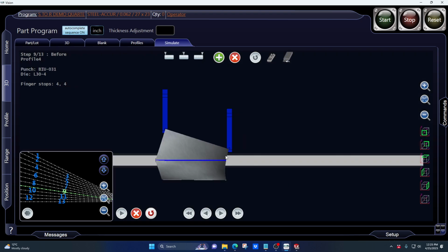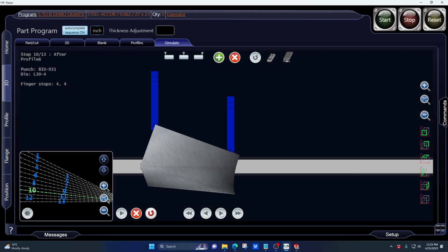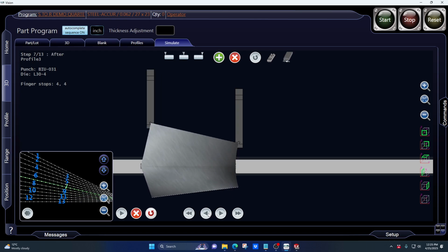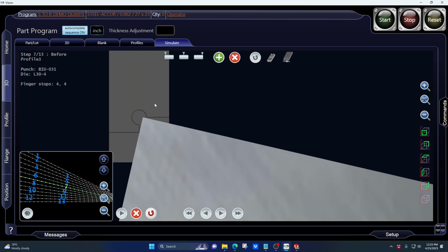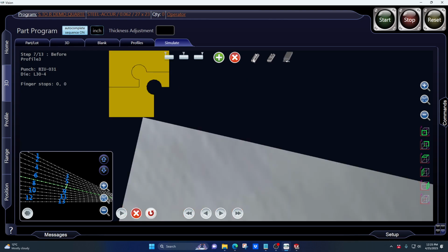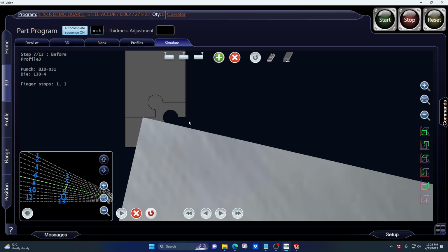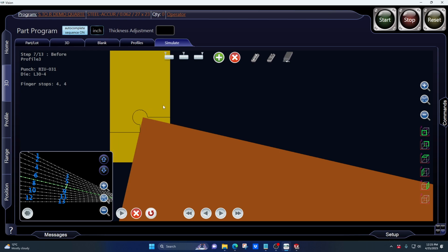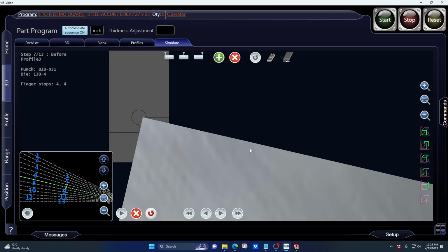And I'm going to transition to the top view as well, so you can see the different gauging positions that are required for squared arounds or like an offset part. So here's all the different options for, say, 6-axis gaugings, where you can actually just kind of tuck in a corner right into the slot there. I can just kind of change the finger rest position. Maybe I just want to gauge it on the front tip there if I want. But I've got different options, and in this case, I'm going right to the corner there, so I can kind of gauge that one there. I'm just going to drag that and position it in place.